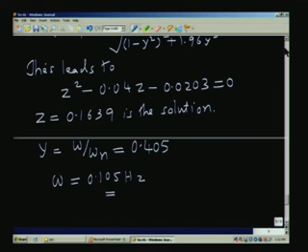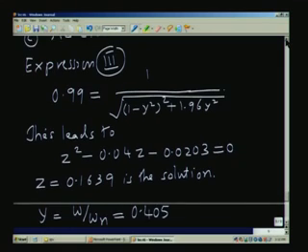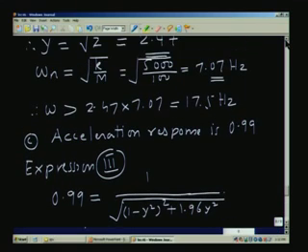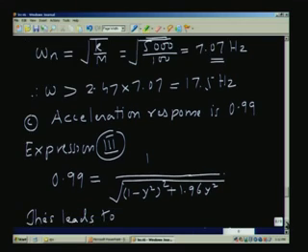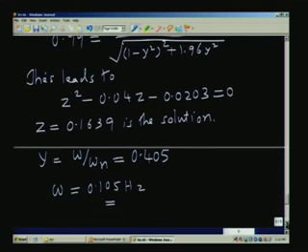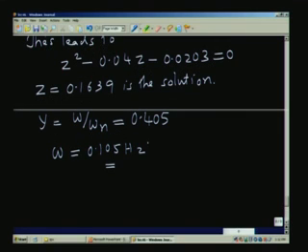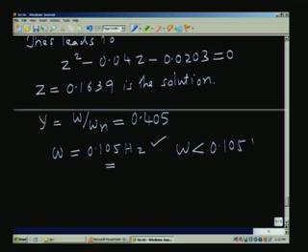Maybe we have made a small mistake. Let me go back, and we should have a value of 2 pi in this formula. Omega n is equal to 2 pi root k by m. So, I think we can make that change. So, let us just look at this. Omega will come out to be 0.105 hertz, which is the value of the omega below which, omega should be less than 0.105. That is important. So, only very small omegas it will respond to.